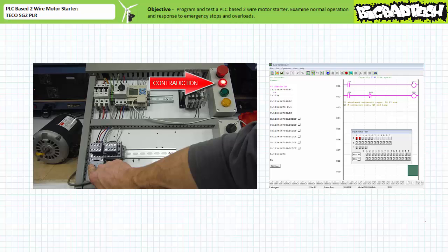If during the course of normal operation an overload event occurs, in this case I'm simulating an overload by manually testing it, the open overload directly depowers the affected field output device without reliance upon any programmed instructions to do so. The F contactor coil is de-energized, the F primary contacts open, and the motor turns off. Note, however, output Q1 is still being asserted by virtue of the maintained closure of selector switch on input 1.